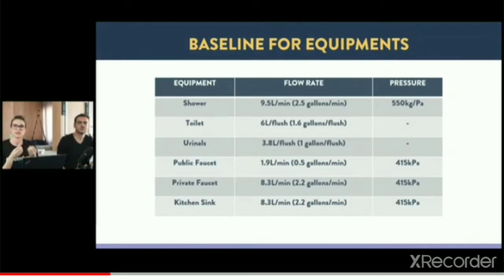So 3 to 6 liters, you will find this in the market. There are more and more. Actually, I think toilets are the ones that have evolved fastest, because now you have the possibility of finding toilets with a vacuum flush that you don't need almost any water. And in toilets also you have the possibility of using reused water. It's something that does not compromise. You don't have to necessarily use potable water for your toilet. This is one place where you have many possibilities of reducing the water use. Same thing with urinals, where you also have a lot more possibilities.